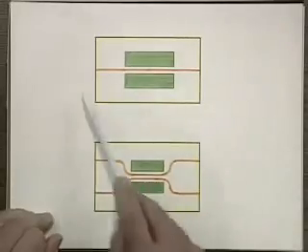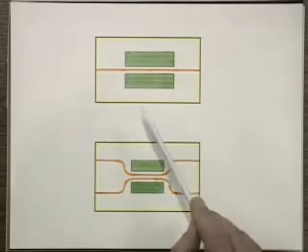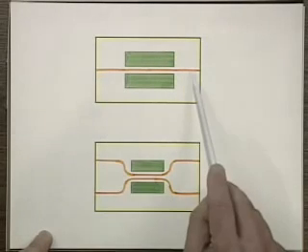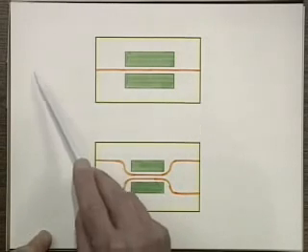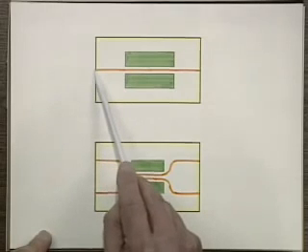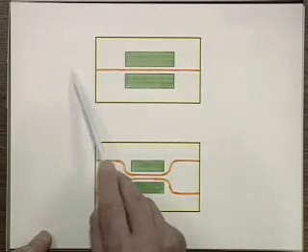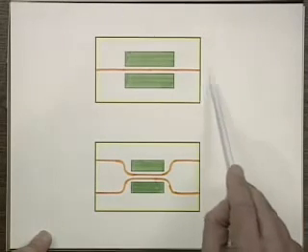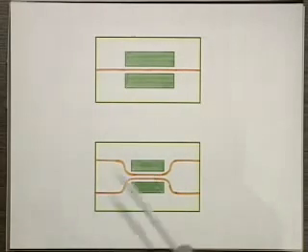Here again is the substrate, and here's the waveguide. Before I even get to what I want to talk about, you have to first couple light into this waveguide. Remember, the core can be very small, just a few microns. So you have to take the output from the fiber and couple it into this core. That's a tricky device, but people have found nice techniques to do that. Basically, you want a fiber to couple into this and this to couple into the fiber going out. If you can do that and these couplers stay together, then you've got something.